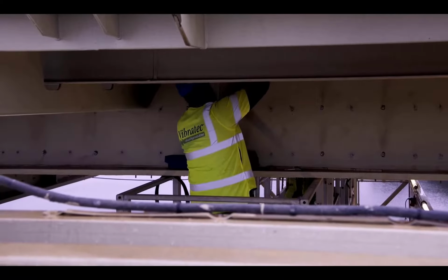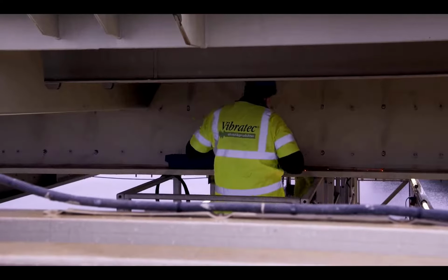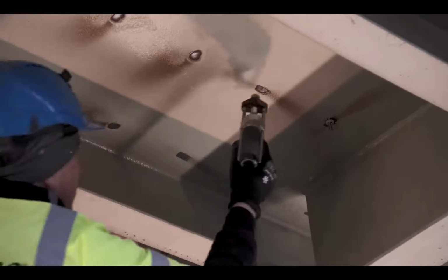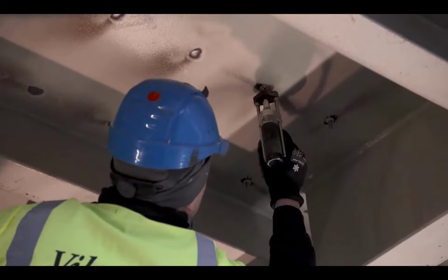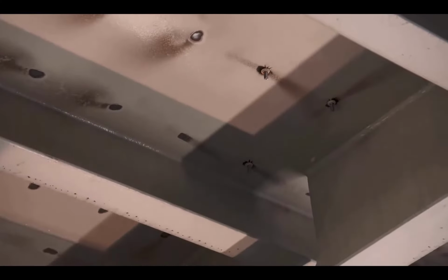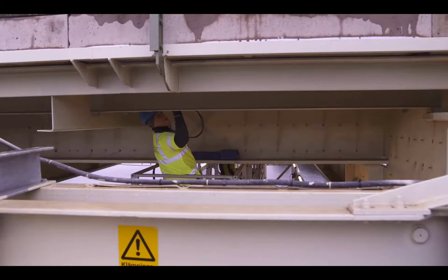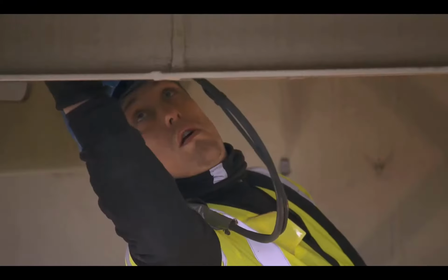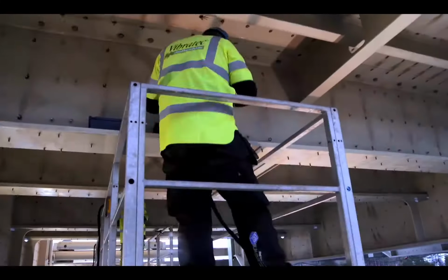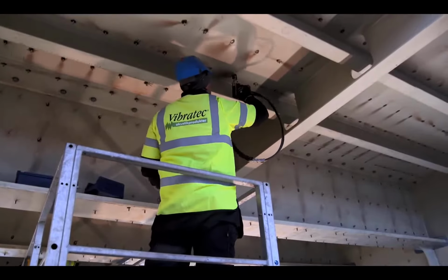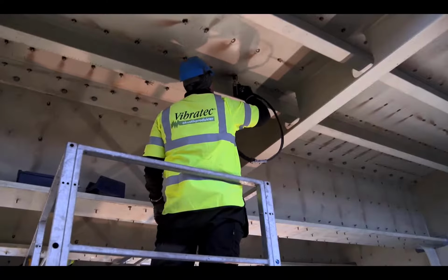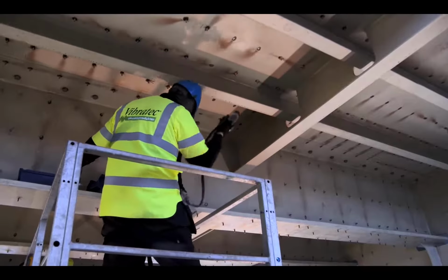Work began in the autumn of 2017. First of all, 66,000 bolts had to be welded in place. The bolts were closely positioned to achieve the required pressure on the panels and the firm contact between the damping material and steel structure. The bridge deck and its beams were all covered with CLD panels. Meanwhile, the trains continued to pass just 2 meters above.